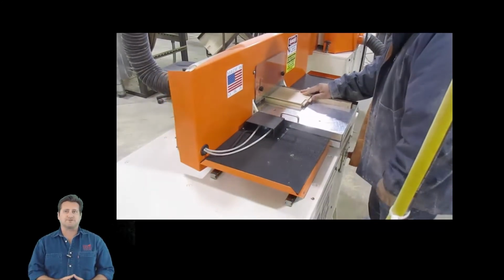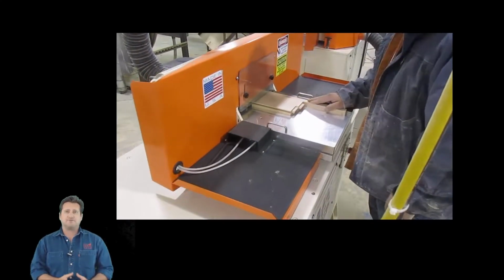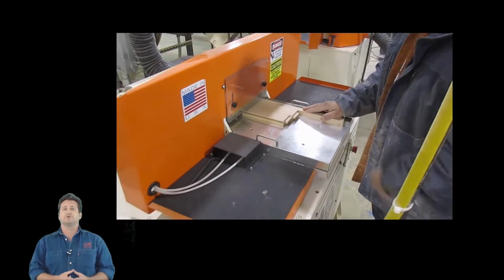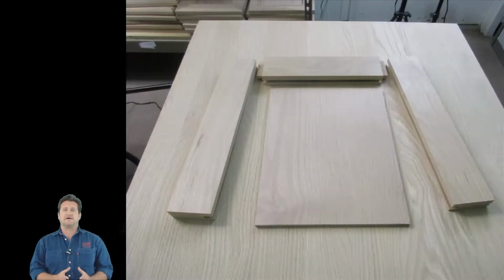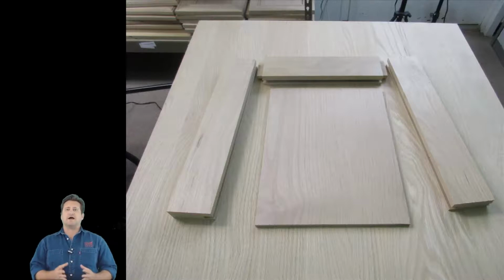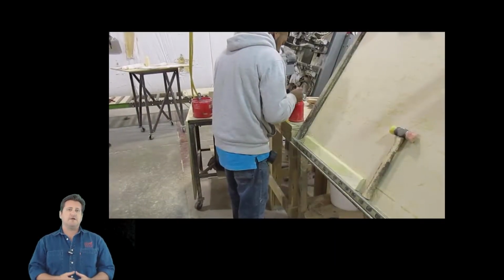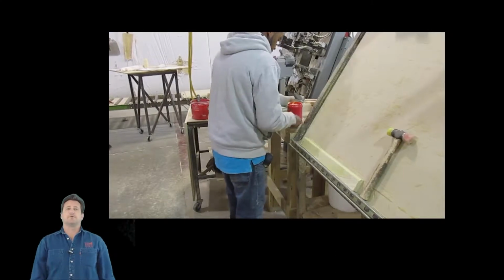Now that the frame parts are cut and the rails coped, it's time for the shaker cabinet door's panel to be produced. Shaker doors use inset panels made of medium density fiberboard, MDF, with a veneer of the wood type required for the order. The veneers are cut and the inset panels meet up with the stiles and rails at a hydraulic cabinet door assembly station. Each shaker door is assembled individually. They're joined with both glue and pins to form a secure and reliable product. A video showing the assembly process is being shown.